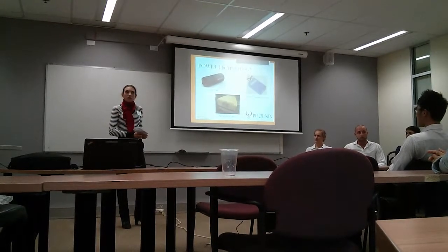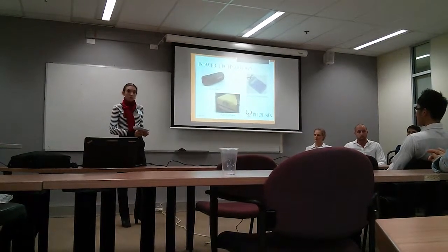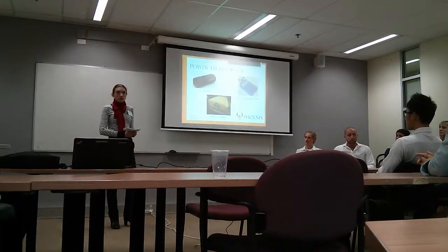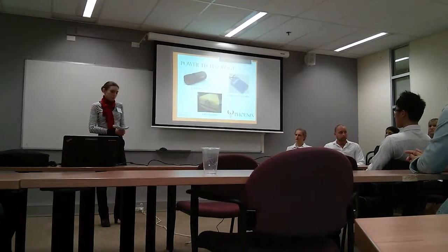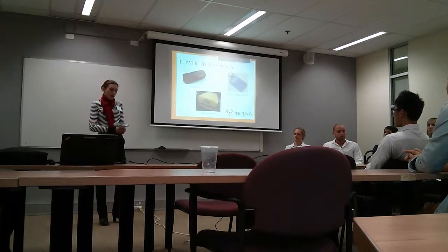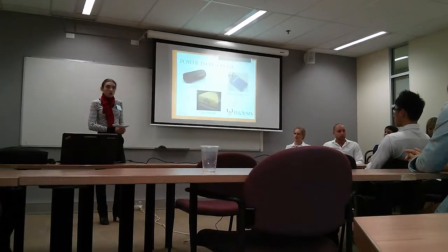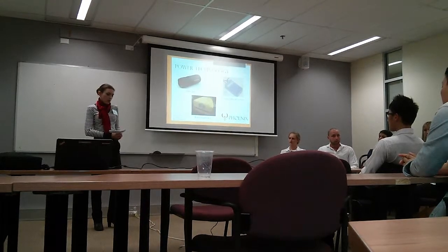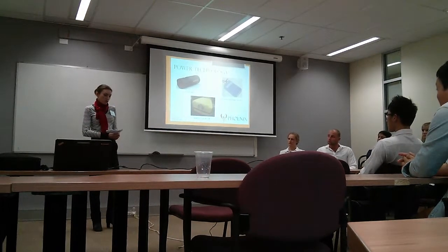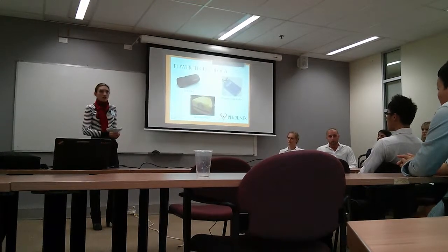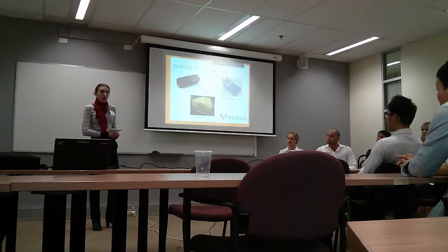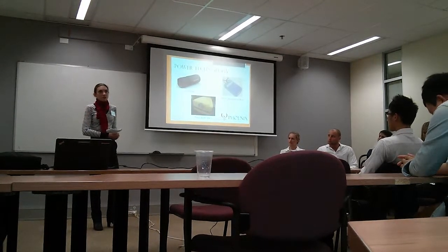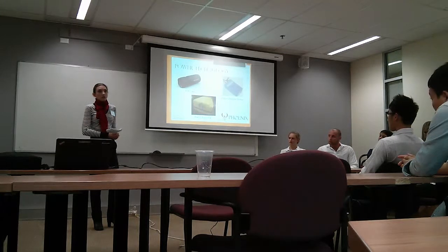A fuel cell would give the longest flight time, and it's much more efficient than petrol. Unlike batteries, the reactions do not degrade the fuel cell over time. But the disadvantages are the high cost. Most types of fuel cell have quite high operating temperatures. And the most important thing, fuel cells use hydrogen or hydrocarbons or alcohol, which are quite flammable. So it's the same problem as with the petrol engine, where if it crashes, you'll lose the vehicle and probably the data.